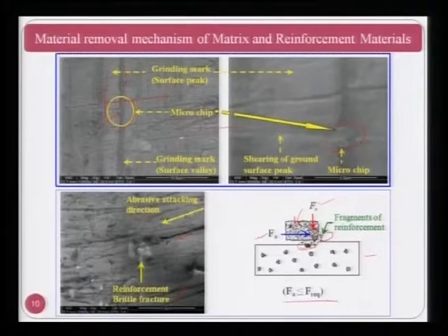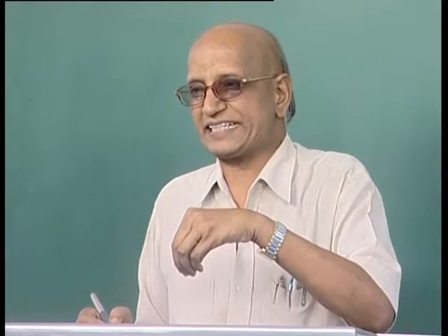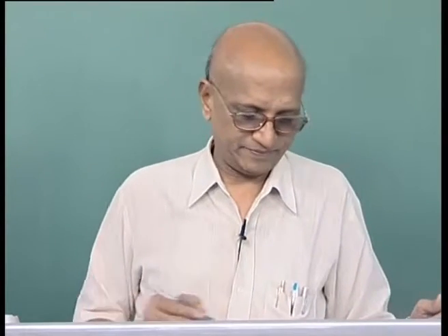In this case, or in any case, for removal of the material, the axial force should be more than the required force. The required force is nothing but the resistance offered by the workpiece material to deformation or removal. Now if Fa is less than the required force, what will happen? Either the abrasive particle will remain entangled in the workpiece surface, or it will rotate, decrease its depth of penetration, and remove the material.